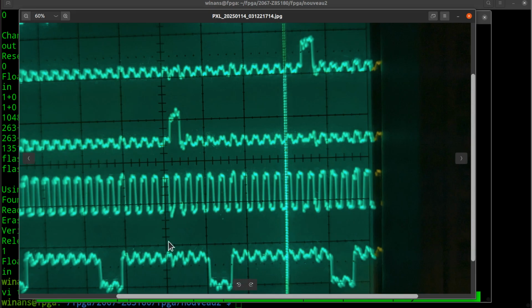This one is the input instruction. So you're going to see the same sort of thing. You got M1 here, so you got 1, 2, 3, reads its operation, the immediate operand, 1, 2, 3. This here is easy to track because this is going to be T1 over here, and this is going to be T2, and you see this thing is not quite as wide as this one, right? Because remember, this is the one that starts when it starts, but it ends on the falling edge of T2 here.